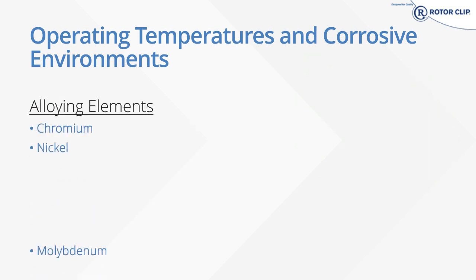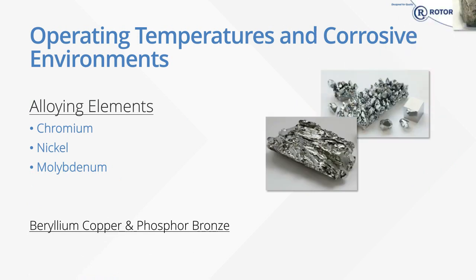The key considerations in stainless that give it the properties that everyone loves are the alloying elements. There's a bunch other than those listed, but the key alloys that are useful are chromium. Chromium is what makes stainless steel stainless. Chromium forms a surface film of chromium oxide to provide corrosion resistance. This increases scaling resistance at elevated temperatures.